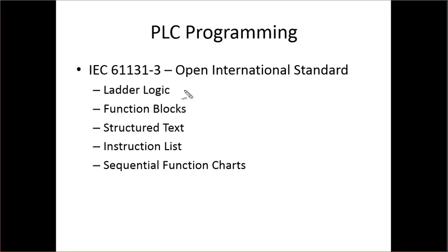Out working with PLCs, ladder logic seems to be the most common thing that you'll see, or the most popular way of programming. And then when you get up into larger control systems, distributed control systems, and stuff like that, you'll see function block programming a lot. These are the two things that I see most often, the ladder logic and the function blocks. In the next couple of slides, I'm going to show you a little bit what they look like.